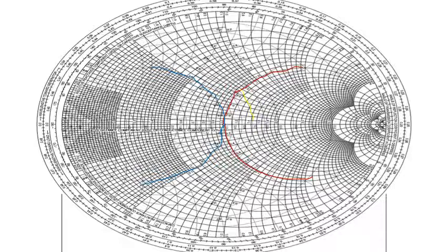So when I'm moving up over here, this movement of going up, we always represent it as an inductor. So how will you plot it? Since you moved along the dotted circle and you were moving up, you will be drawing a shunt inductor. A shunt inductor. Let us take some other example.